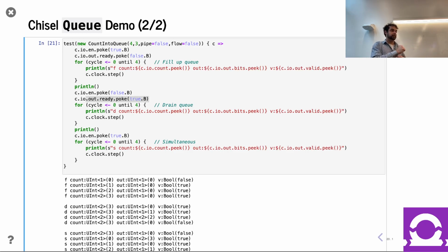Question, yes? Okay, this one does not. There is support in Chisel for a different structure to do clock domain crossings. You have these CDCs, clock domain crossings, async kind of FIFOs to get across them. Yes, that's another component inside the library. So Chisel will support multiple clock domains. I don't do it in this course, but that's out there and that's a common thing. Cool. Other questions?